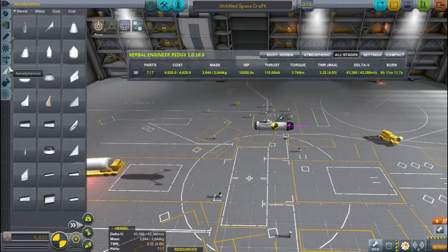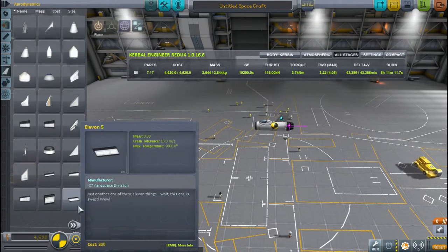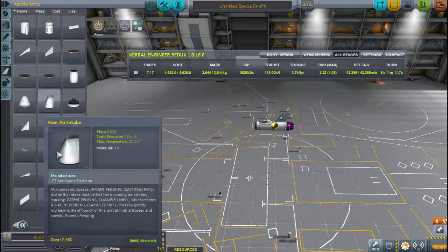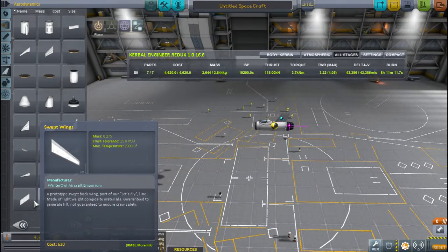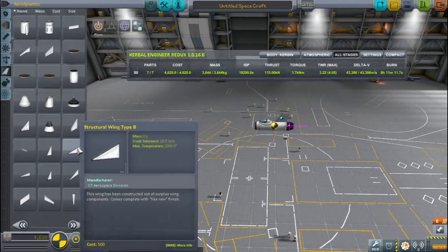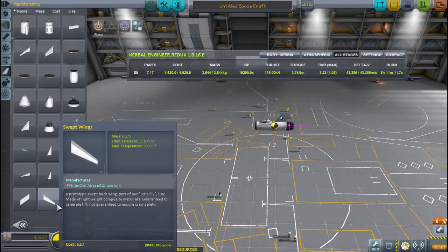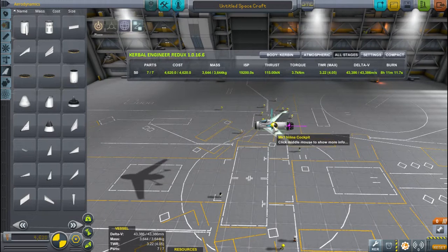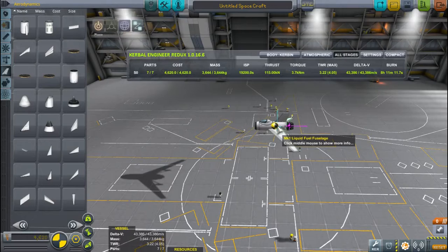What we have to do in order to rectify that is find maybe not only a wing that is so out there like that, that's so difficult to use, but we need to put this guy slightly behind the center of mass, because this guy's a lever.